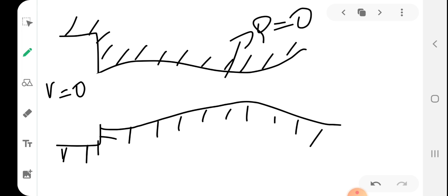It is a reservoir where the fluid is stored, so initially the fluid is at rest. The velocity of fluid in the reservoir is 0 and the flow through the duct is isentropic. Therefore, the state of the fluid inside the tank where the fluid is at rest represents what condition? The stagnation condition corresponding to each location in the duct. You have learned the stagnation condition in your previous module.